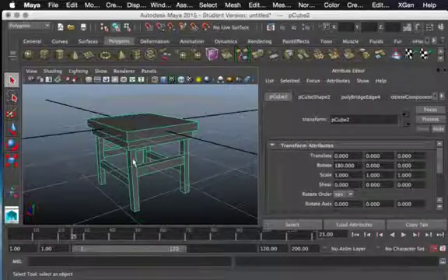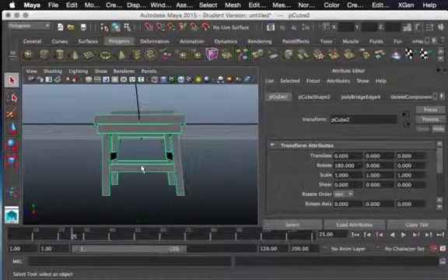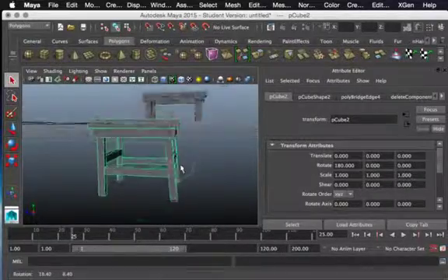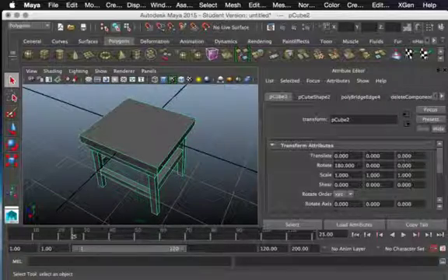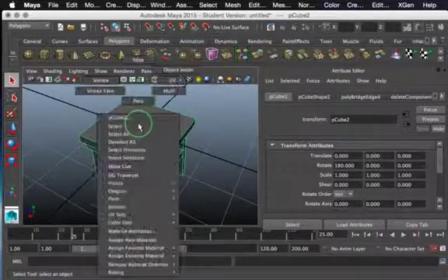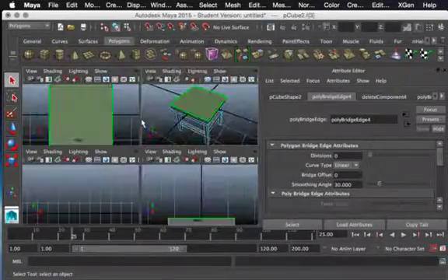All right. Now these are the legs that are jutting off a little bit to the back, so this is the back of the chair. We're going to need to cut here. Go into face mode, select that, space bar.